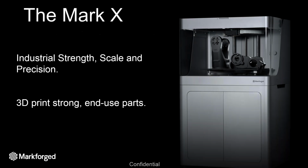One of the things Markforged came out with is a new material which they call Onyx. Onyx is nylon, which can be a little bit flexible, which is a good thing because some people want flexible parts. But it has chopped carbon fiber embedded into the nylon, so it's typically about 4 times as strong and as stiff as straight nylon. Then you put in continuous strand fiber somewhere in the model depending on where you need strength.